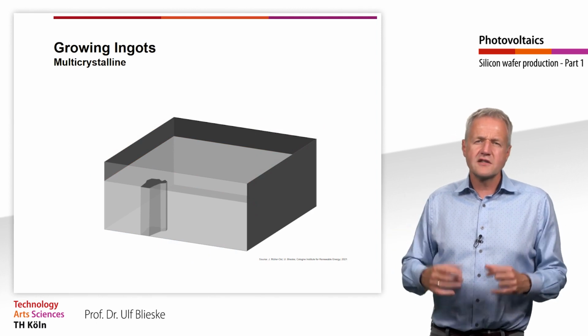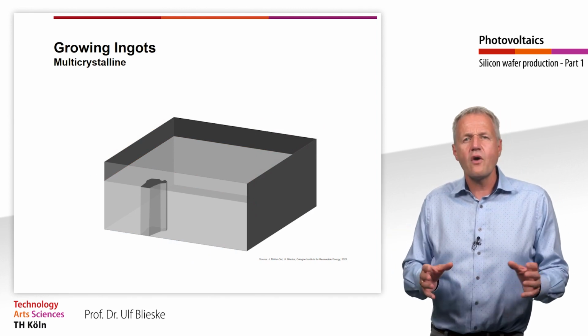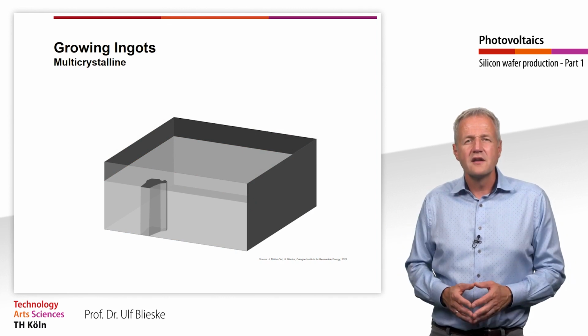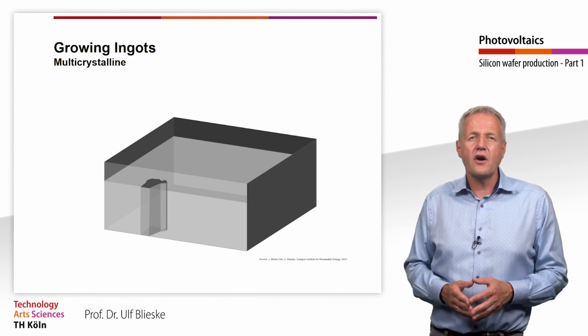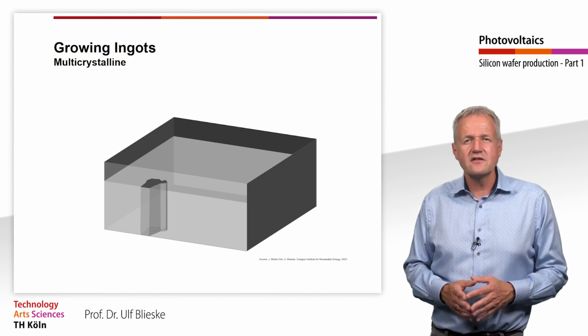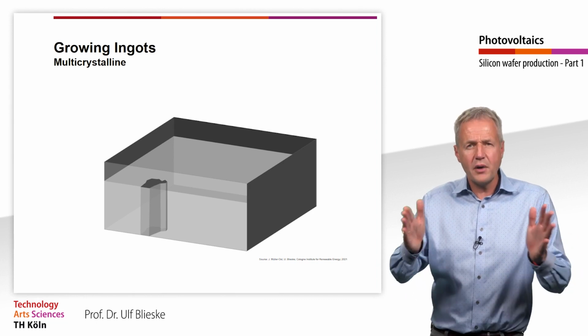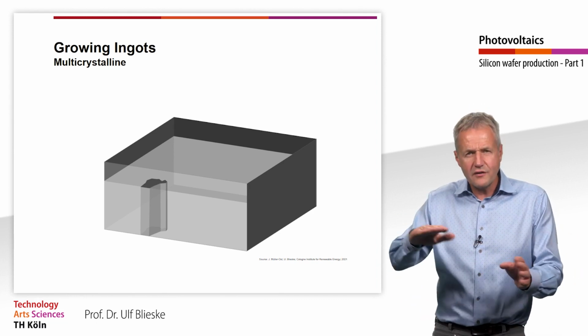This can be achieved, for example, by slowly pulling the heating rings upwards. This special cooling technique causes the crystals to grow upwards like columns. This is advantageous because later the charge carriers do not have to cross any crystal boundaries in the vertical direction that way.